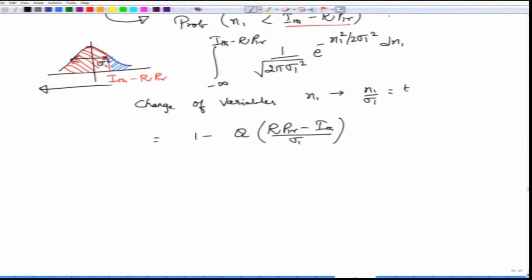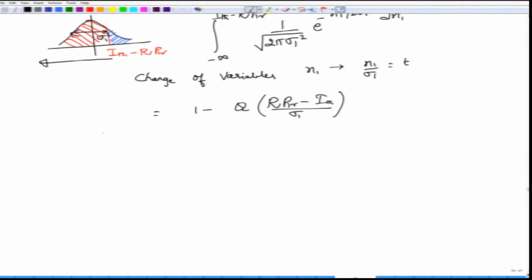Once you have done that, now you can put together the total error. How do you put together the total error? Suppose you have bits 0 and 1 in on-off keying, that is what we have. When you transmit 0, there is a certain probability that the receiver will identify that 0 as 0, given by probability of 0 given 0. However, this is what you are interested in: the probability that the receiver has identified it as a 1 although you transmitted a 0.